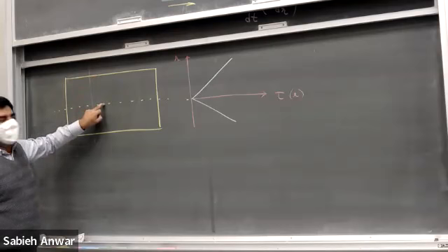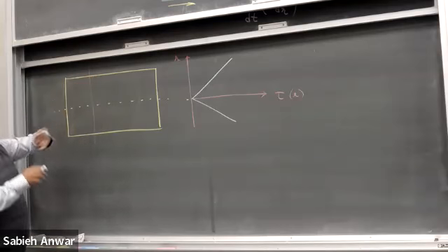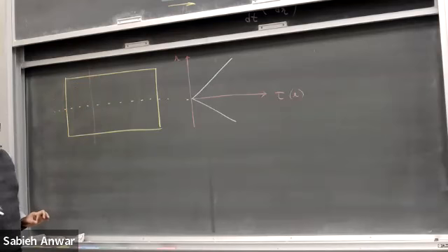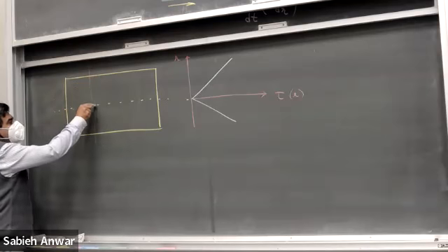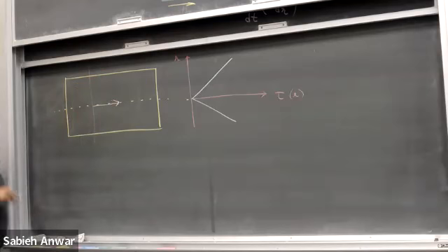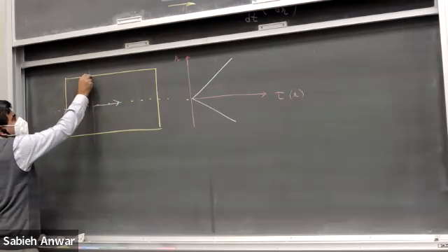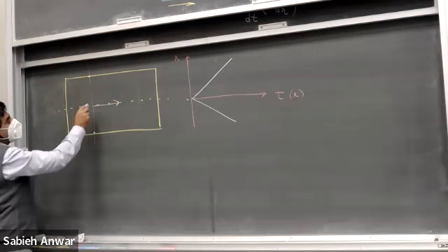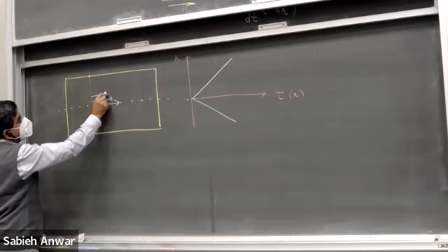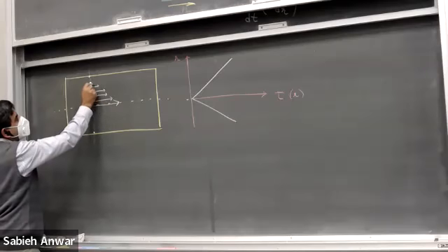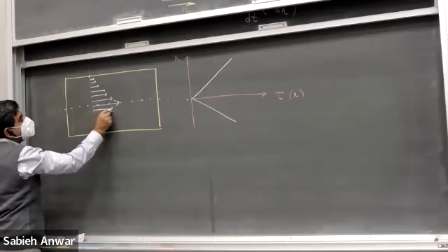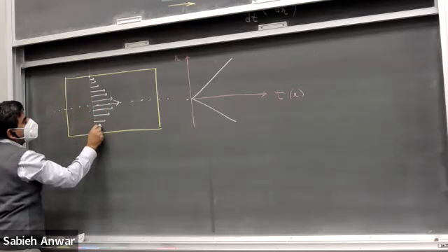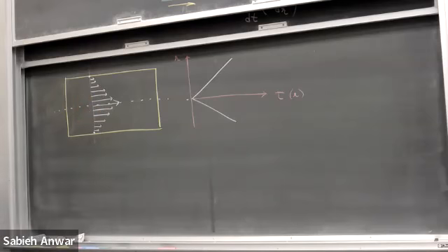Got it? That's why if I were to look at the velocity profile of this fluid along the pipe, the velocity is more likely to be high in the center of the pipe. It's going to be 0 here under the no slip condition. Remember, we're talking about a Newtonian fluid in the laminar flow region, slow speeds, not very viscous. So these are arrows for the velocity profile. This is what they might look like.